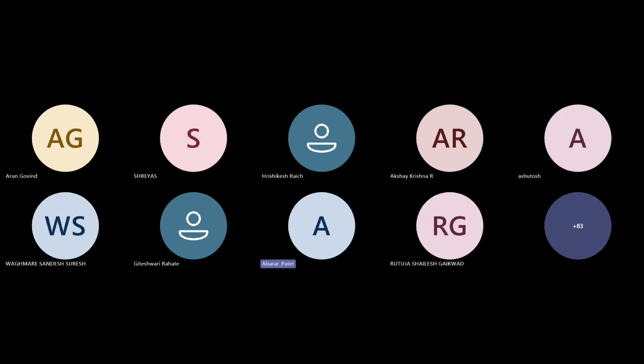And if you need to evaluate your gradability, you can climb your vehicle on a steep slope at certain angles, and try to figure out if your vehicle is able to complete that track grade, and that way you can validate your system. But gradability is included in your design at the start of the design.